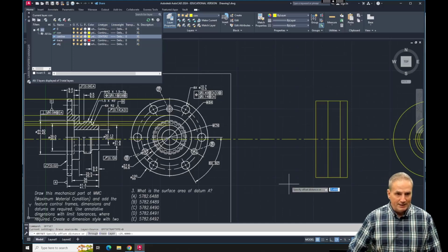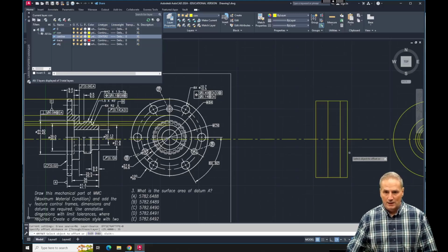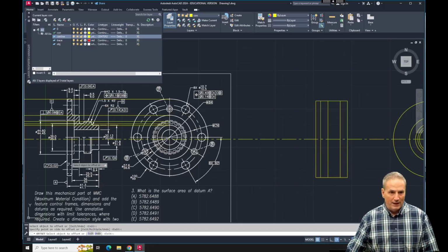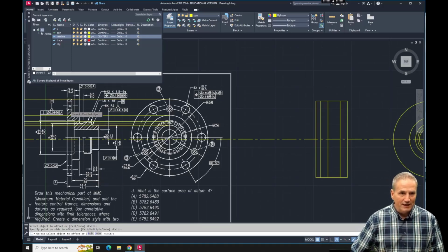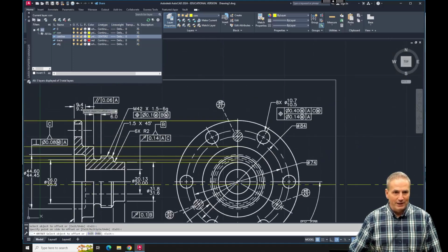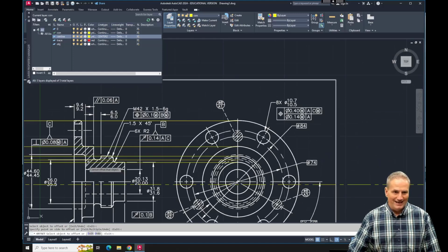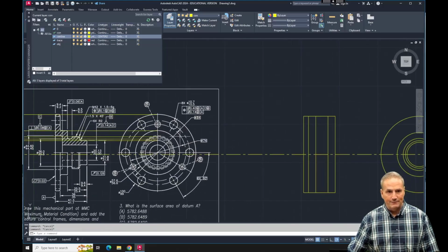I'm going to offset, again, the smaller value is going to be 35. And we can offset that. Cool. And that gets me to this edge right here. So, cool. Now, I do have another offset, and the other offset is for this inside. But I'm going to hold off, and that's that value here. Now, what's that going to be? Well, again, if I go to the smaller value here, I would end up leaving more material. So I'm going to want that to be 9.2. But let's not worry about that so much right now.